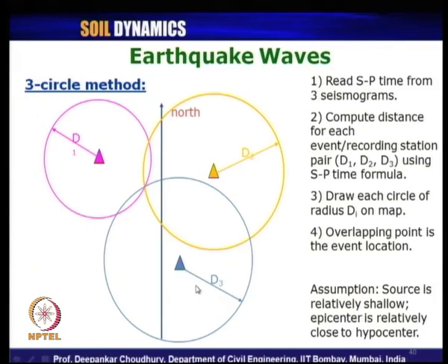So, where actually the earthquake has occurred, where these 3 circles will meet, this is the point. Look at here, I am pointing here with this pointer. This is the point where these 3 circles meet, that is the actual location where an earthquake has occurred. So, this is the location of the earthquake epicenter.